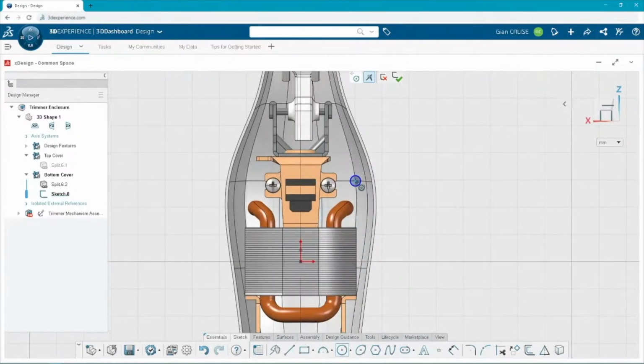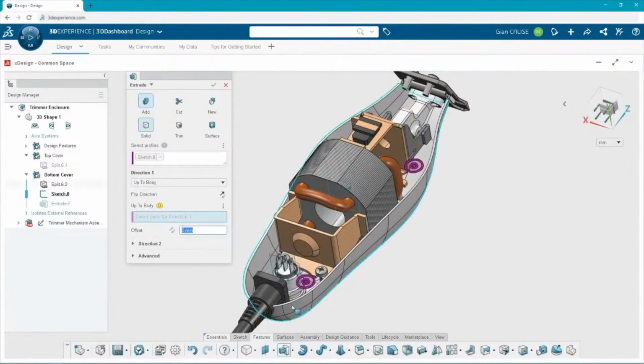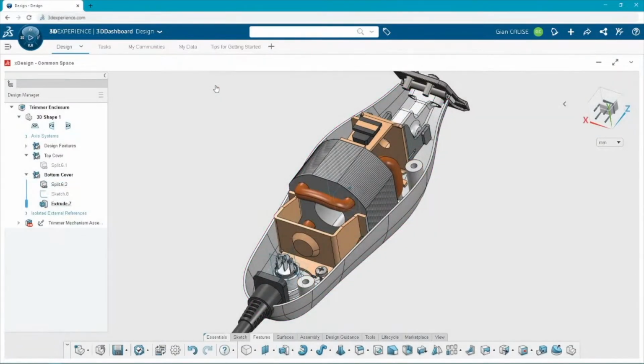Notice how I can put it right on a point in the subdivision body. I can use those points. I can use the geometry to my advantage. And now I'm just going to add some dimensions. I'll use 3 millimeters here. Say we're going to use some M3 screws or something to keep this together. And then we're going to extrude these right up to the body. So remember how we said that you can always mirror to the other side? Well, we're going to do that later. So we only need to add holes on one side of our enclosure for now.